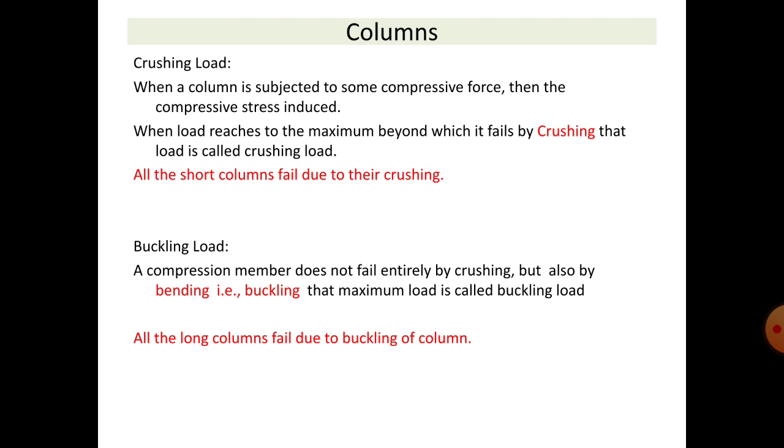How to identify it, we'll study in the next slide. Okay, now we'll find out what is buckling load. A compressive member doesn't fail entirely by crushing. As I said, all the columns are not short columns. All short columns will fail by crushing, but the long columns will not fail by crushing. So the long columns will fail due to bending.